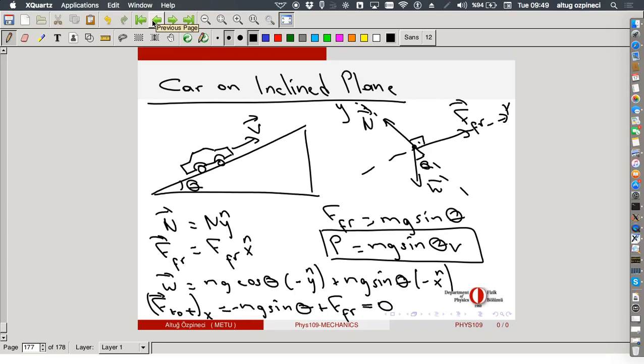What if it's moving in the same direction? If you imagine the forces acting on the car, there is a drag force in that direction. Now, if you are moving at constant velocity, there has to be some other force in this direction. That is the friction force, pushing you forward. The reason is the wheels. If you are moving against some force, like the drag force, the wheels are rotating like this. Although the car is moving in this direction, the bottom of the wheels, which is creating the friction force, is trying to slide in the opposite direction. So that is why the friction force is in the forward direction.